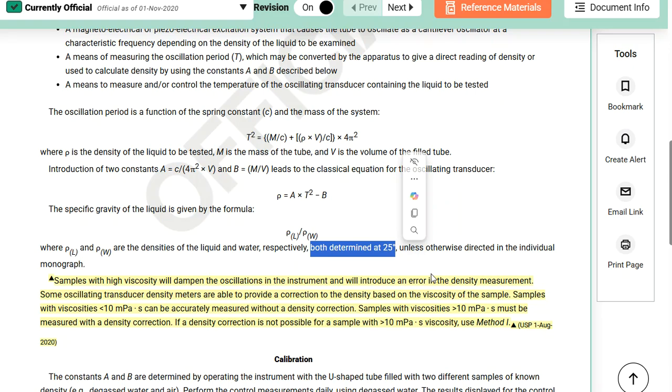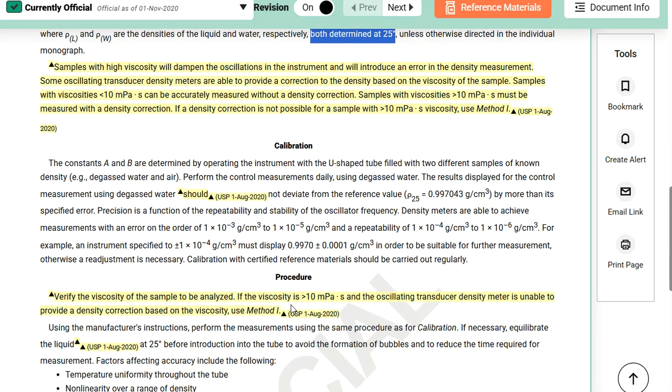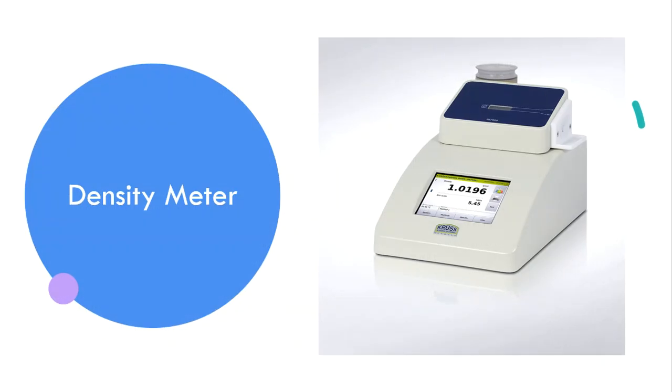If it does, then we key in that temperature value to the machine. We don't worry about heating it up on a hot plate. We don't worry about heating the pycnometer that contains the sample. We literally key the temperature into the density meter. That will heat up or cool down to what it needs to be, and that's where the measurements are going to take place. And then it talks a little bit about the calibration and the procedure here. All right, so a little bit more about the calibration, the validation piece, and so forth.